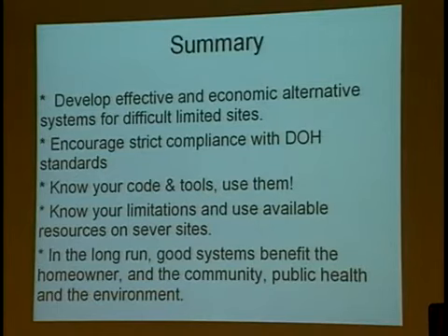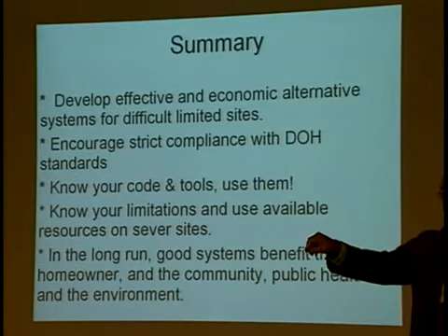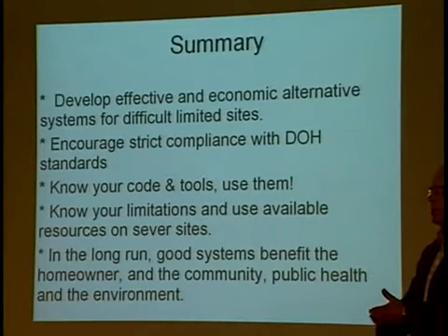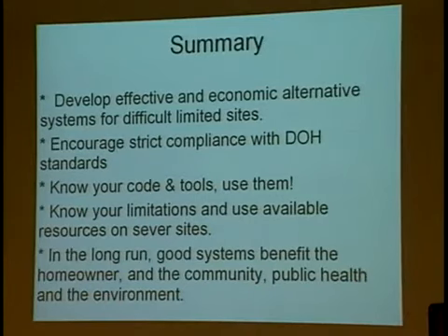Encourage strict compliance with your New York State Department of Health standards. The standards are there. You have the tools here to use. Keep the system back away from the shoreline as far as possible. If you know what your 10-year flood elevation is of Chautauqua Lake, make the system come up and get it out of that water so you're getting better treatment, hopefully better nutrient removal. Know your codes, know your tools, use them. Know your limitations, use available resources on severe sites.